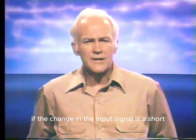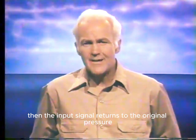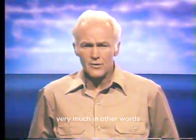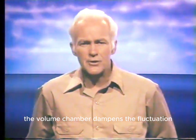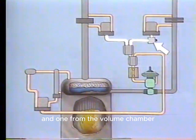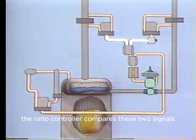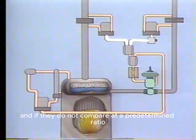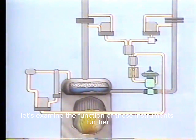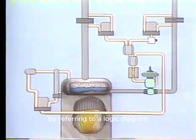If the change in the input signal is a short, temporary fluctuation, then the input signal returns to the original pressure before the pressure in the volume chamber changes very much. In other words, the volume chamber dampens the fluctuation of the input signal before the output signal is affected. The output from the volume chamber is sent to the ratio controller. So the ratio controller has two input signals, one from the steam flow transmitter and one from the volume chamber. The ratio controller compares these two signals, and if they do not compare at a predetermined ratio, it produces a corrective output signal. Let's examine the function of these instruments further by referring to a logic diagram.